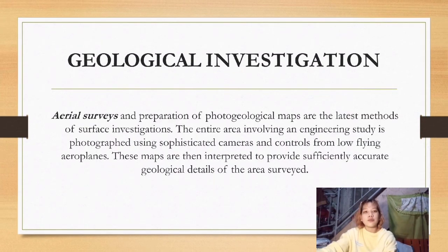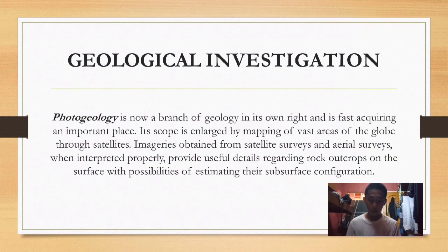Aerial surveys and preparation of photogeological maps are the latest methods of surface investigation. The entire area involved in an engineering study is photographed using sophisticated cameras and controls from low-flying aeroplanes. These maps are then interpreted to provide sufficiently accurate geological details of the area.